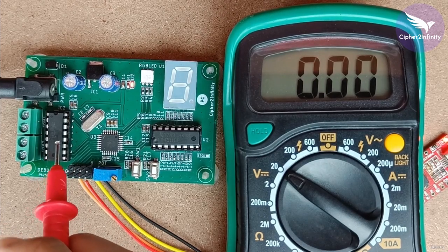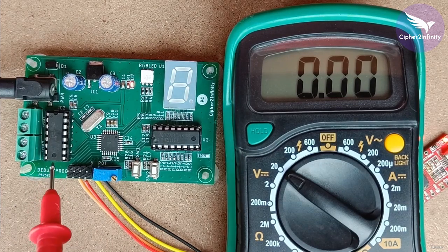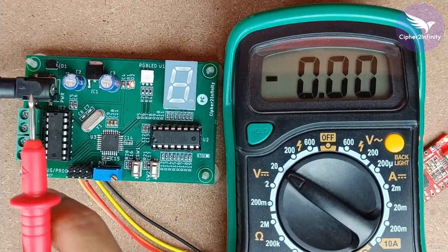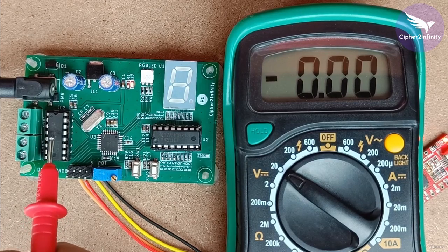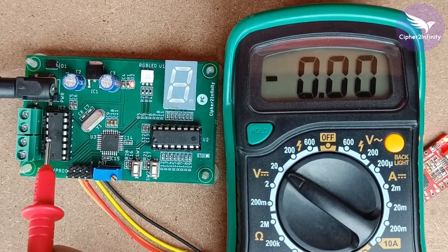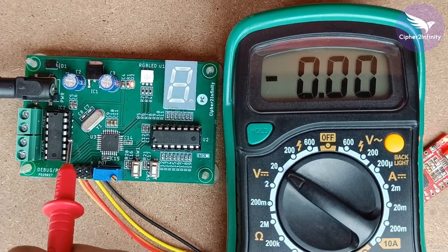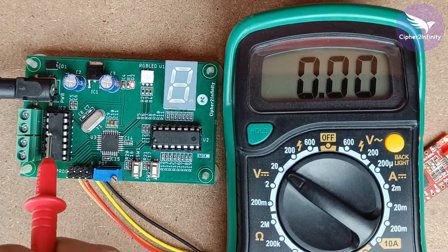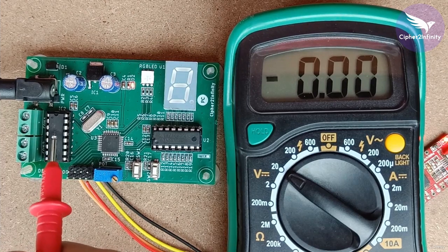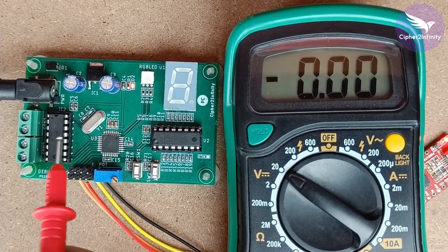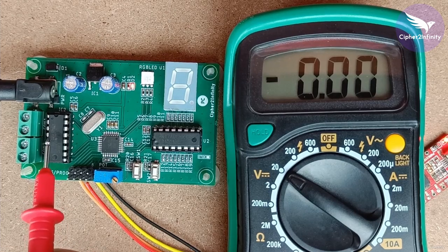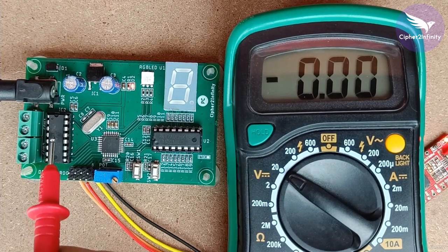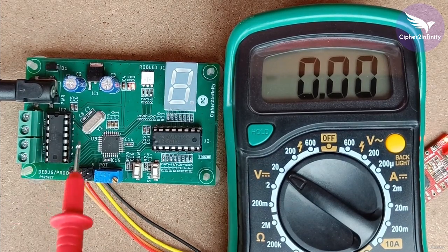And if there is a problem with the IC, then straight away you can remove the IC with the help of the probe of the multimeter or by using a tweezer. That's the point that I wanted to emphasize. Always remember, you have to use the IC base, and place the IC on the IC base only. Don't solder the IC directly on the PCB, because if there is a problem, you're going to face a lot of issues in future related to removing the IC from the PCB. So that was all about the mistakes.